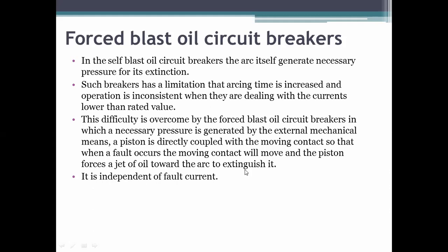Means when the fault current is more, we are using the cross jet. When the fault current is low, we are using the axial jet, for medium we are using the plane break, and the combination can be used for low to high, right?